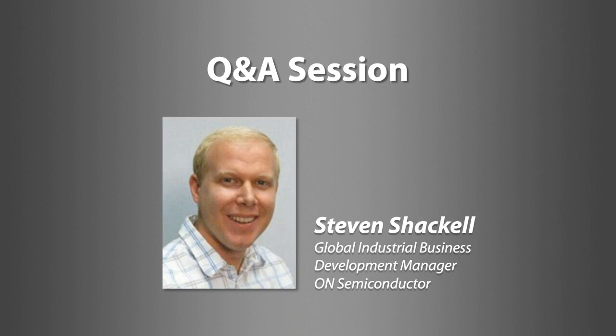Okay. Will GaN devices eventually be superior to silicon carbide? Again, that depends on the application that you're looking at. Anything at 650 volt and below, GaN, I believe, will be more superior than silicon carbide. But GaN will never be the choice in applications that may require 1200 volt or 1700 volt. Silicon carbide will dominate that space. So it's an in-between answer, but it really just depends on the application itself.